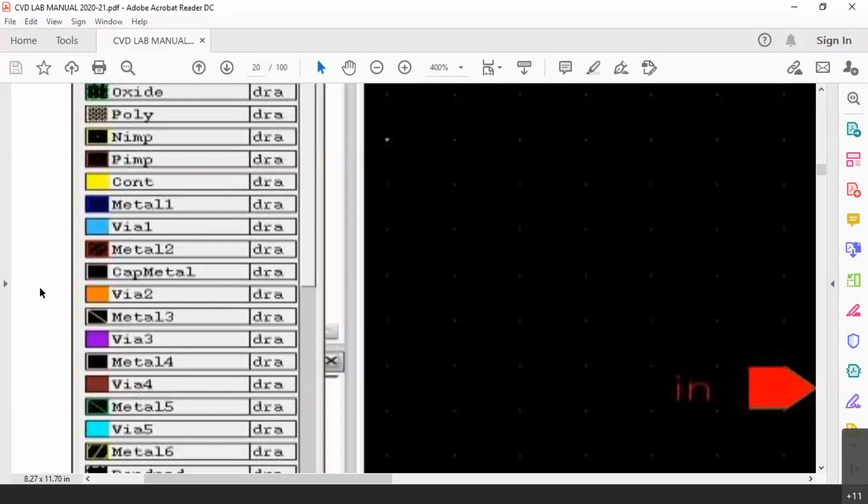In the same way, inside the chip here now, we have multiple floors. Lowermost is substrate, above which we have well, above which we have implant, above which we have oxide, above which we have polysilicon, above which we have metal. Again in metal, we have metal 1 till metal 6 now. How do we connect these multiple layers?